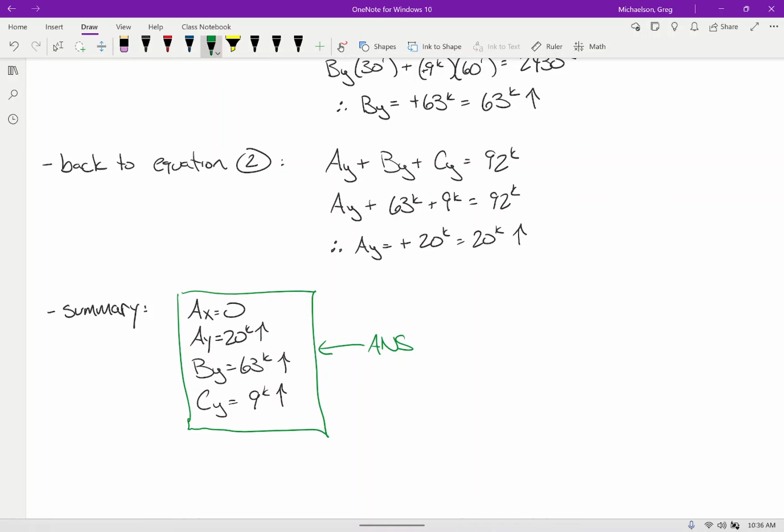Because if these numbers are truly the correct numbers, then when you draw your shear diagram, it will start and end at 0. When you draw your moment diagram, it will start and end at 0. The problem has a way of self-verifying that it's correct. I find that really neat. I still to this day find it really cool. If you look at the shear and moment diagram for this structure, it will look wild, but it will be right.